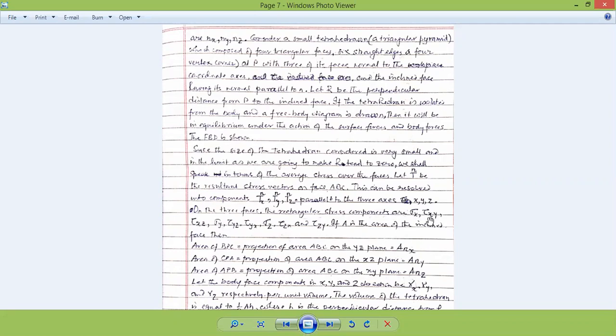By the subscript x, we mean it is acting over the x plane, and the second subscript shows the direction. So tau xy acts on the x plane but is directed along the y direction, and tau xz acts on the x plane but is directed along the z direction. So on the x plane we have sigma x, tau xy, and tau xz.